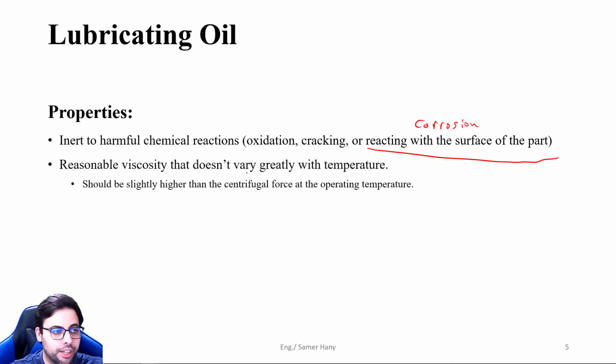Okay. Second, it should have reasonable viscosity so that it doesn't vary greatly with temperature. As we all know, when we increase the temperature of any viscous liquid, the viscosity gets lower and the liquid gets more fluidity. Okay, so at the operating conditions, we don't want this viscosity to drop and the oil just drops off the surface of the moving parts. It should have reasonable viscosity to stick to the surface at the operating conditions.